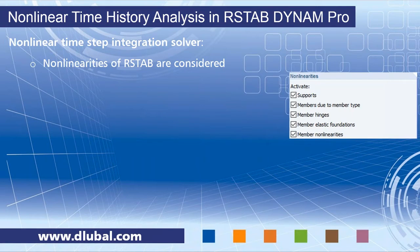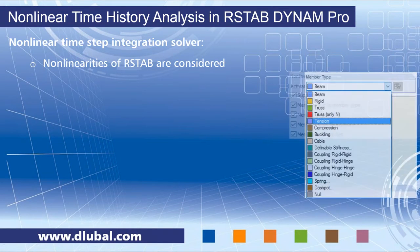This is also a direct time step integration scheme, so eigenvalues are not required and natural vibration cases are not assigned. All the nonlinearities that are available in RSTAB and that you defined in your model are considered in the nonlinear time history analysis. In the global calculation parameters, you get an overview of all the nonlinearities that are available in the main program. Depending on whether you have defined them in your model, the checkboxes are active, and otherwise they are deactivated. And we go into detail here.